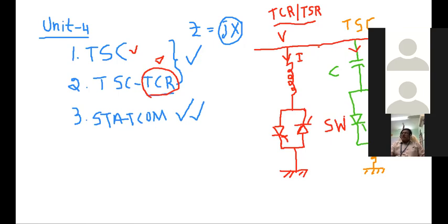And also one more purpose is stated here, to avoid the resonance condition with the supply. Because generally the switching on of the capacitor will create a resonance condition. That is also a problem. Because of this resonance, you get currents that again damage the power system, because this capacitance in series with this line inductance may form the resonance condition. To avoid that, we use this inductance. That is also the other purpose. The main purpose is to limit the current.